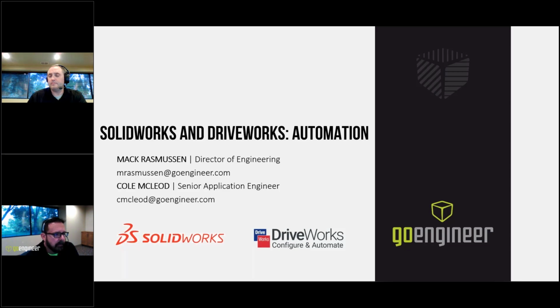I guess the only other thing Cole and I want to mention about DriveWorks to make sure everybody knows is not only is it obviously fully integrated with SolidWorks, it's also fully integrated and works correctly with SolidWorks PDM and enables data reuse, right? So if you're generating a variation of a model that uses a standard configurable base plate and that particular size configuration was already created with a previous run, it's going to reuse that part, not recreate another one of a similar size with a different number. So it's designed to work with PDM out of the box.